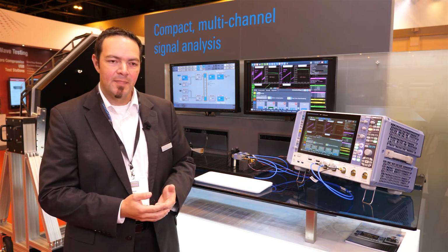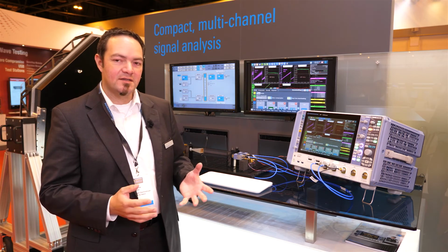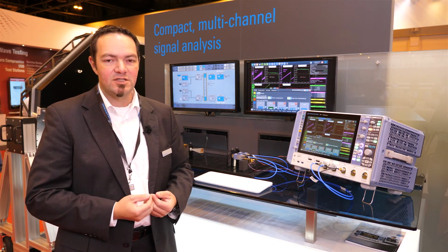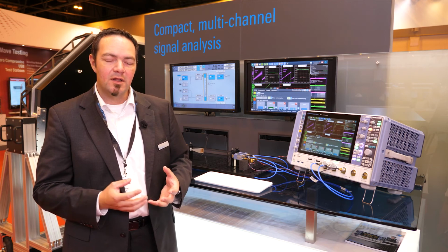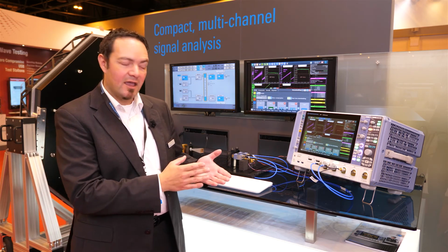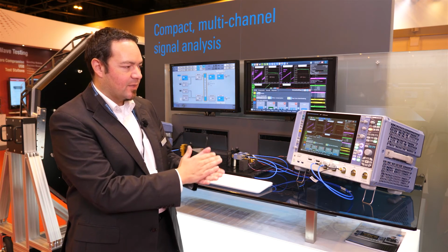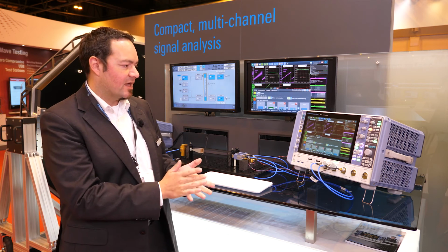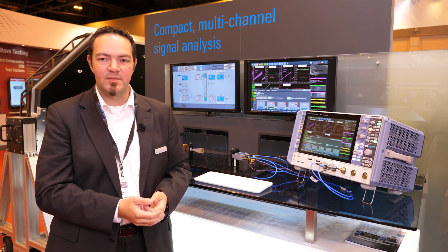So to summarize, with the RTP, with all the hardware functionality and hardware acceleration we have on board, we are able to measure and demodulate chirps at higher frequencies. So in this example here, we do a 77 GHz automotive radar link measurement on an 8 GHz RTP oscilloscope.